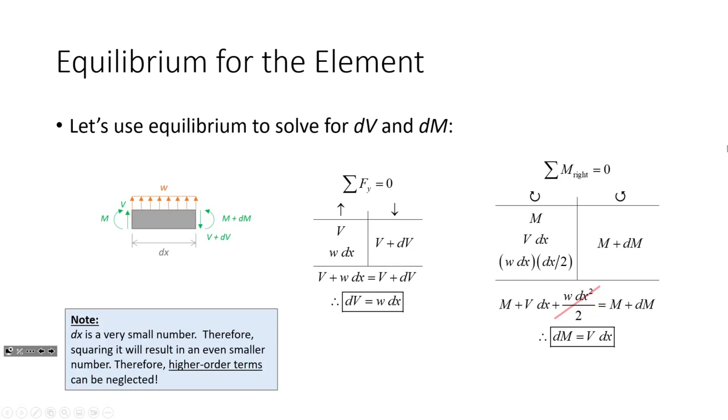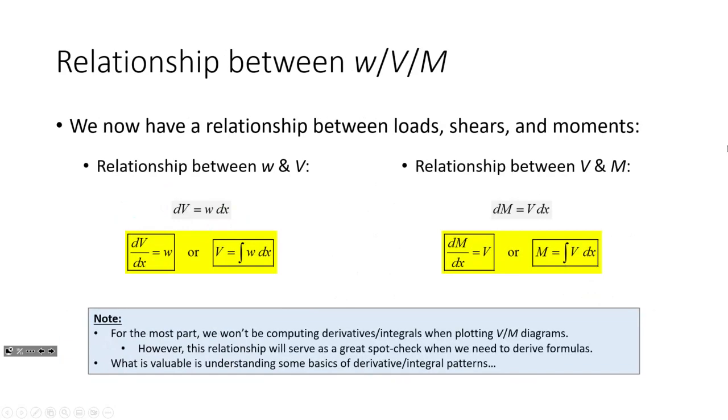And if I look at these relationships, I can take these equations and rewrite them a little bit, and by golly gosh, like I said, we're going to be in the land of calculus a little bit. Now, I want to be clear, we're not going to be directly computing a lot of derivatives and integrals when we plot shear moment diagrams. So I just want to level with you. We are not going to be doing that. But what I will tell you is that understanding this relationship is going to be a great spot check.